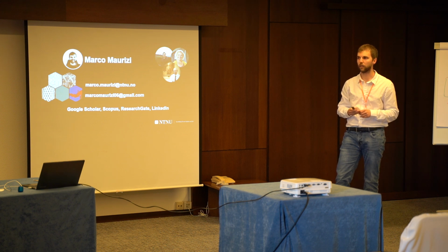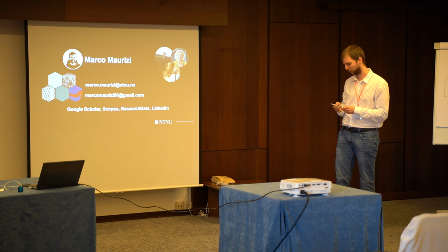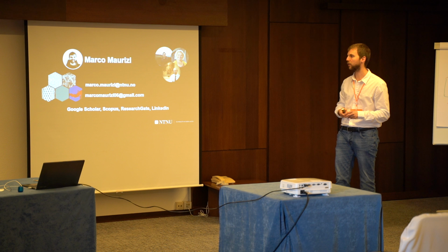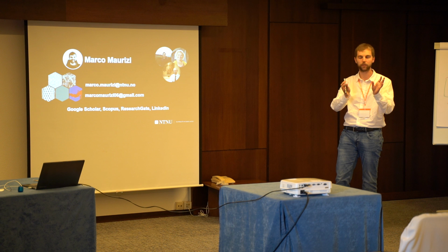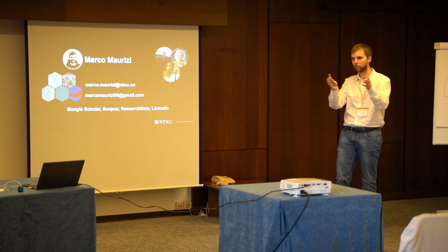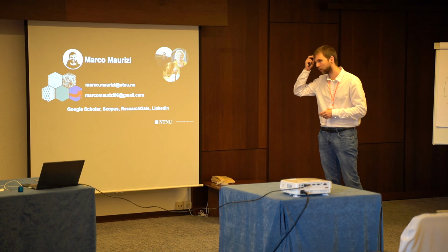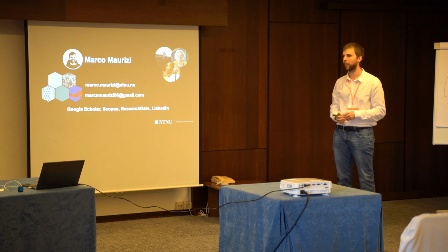I've been working a while on this, so I haven't shown everything, but you have the possibility to create, for example, auxetic structures with negative Poisson's ratio. The design space, as I said, is really large, so if you combine many different building blocks, you could obtain really everything you want. And this is just in 2D. If you want to do it in 3D, of course, the design space will be larger.